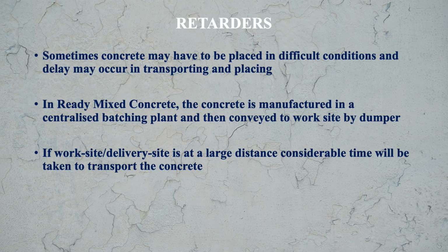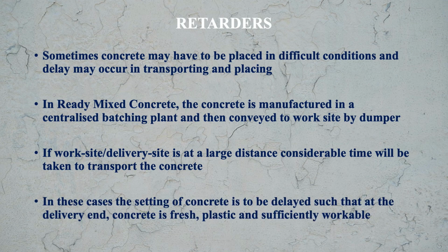If the work site and delivery site are at a large distance, considerable time will be taken to transport the concrete. So retarders take care of this. In these cases, the setting of concrete is to be delayed such that on delivery the concrete is fresh, plastic and sufficiently workable. So what are the materials that are used as retarders?